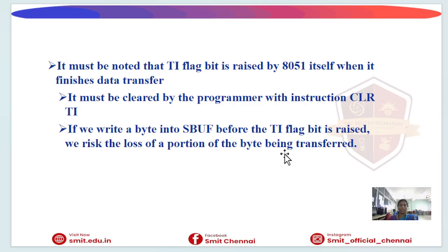If the TI flag is not cleared properly, the microcontroller may incorrectly assume that the transmission is already complete, leading to communication problems. Therefore, after every successful transmission, TI must be cleared before sending the next data byte.